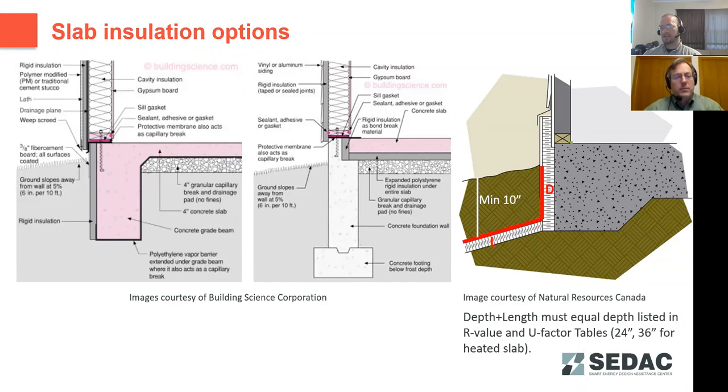So we realize there are some instances, as I listed as an example, if you've got a slab that's got heavy traffic, such as forklifts, heavy trucks, things like that. Usually what we've seen for detail there is that there's a structural component with a thermal break, but it's not actually insulation. So there is a discontinuity there, but it's to maintain the integrity of the building structure, which the code does call out for safety purposes and integrity of the building. That takes precedence over the insulation requirements.